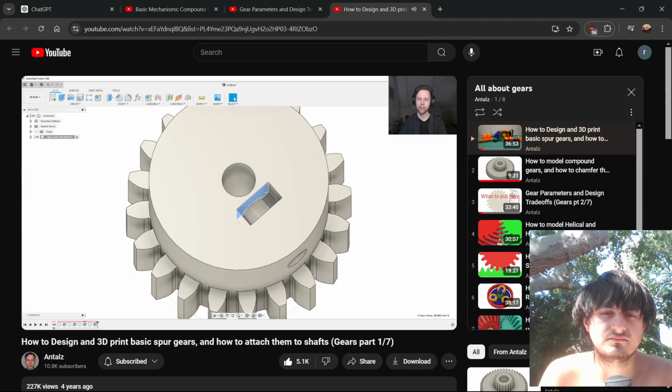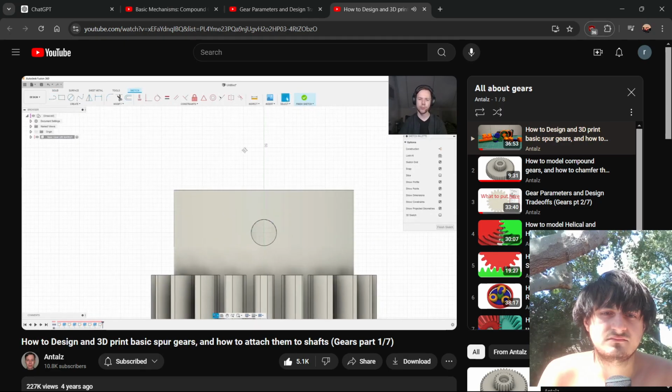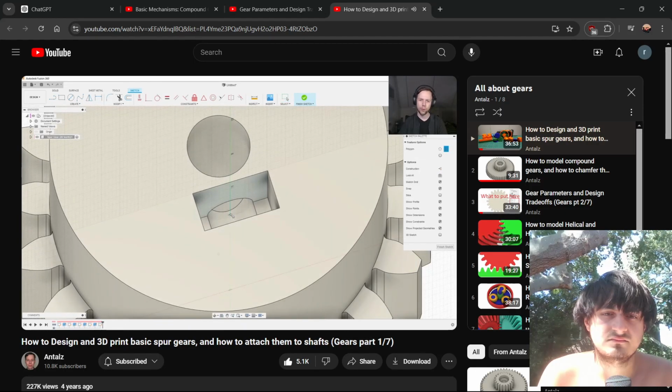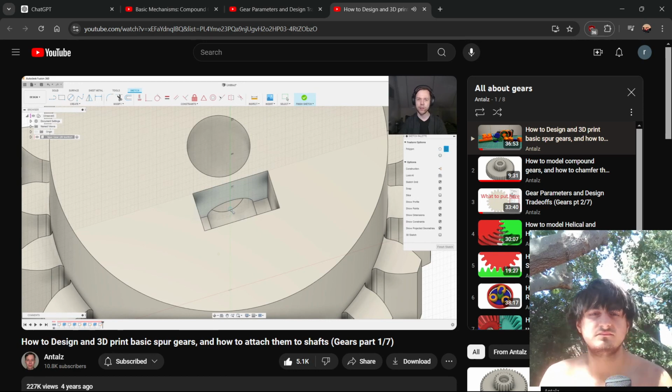And for that, I again click this surface over here, create a new sketch. And what I will do now is under Create, Polygon, take a circumscribed polygon, and then you want to look around here until you get this concentric constraint.